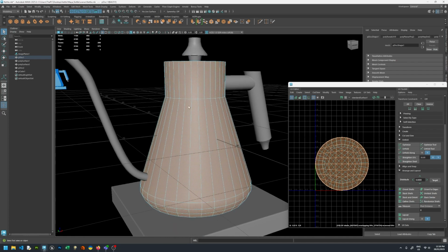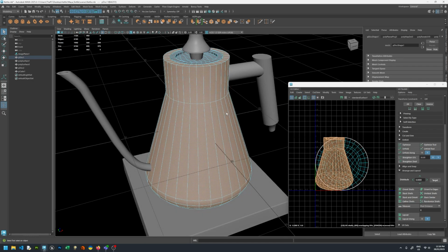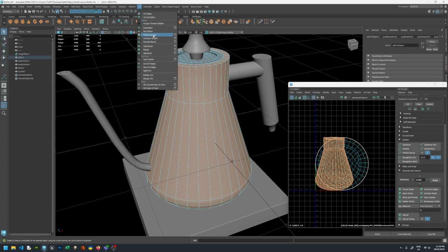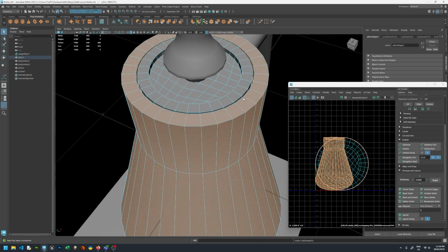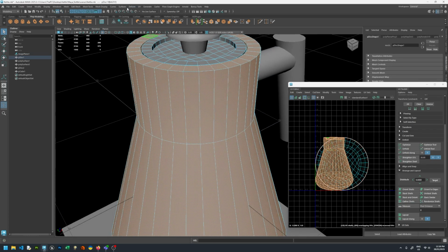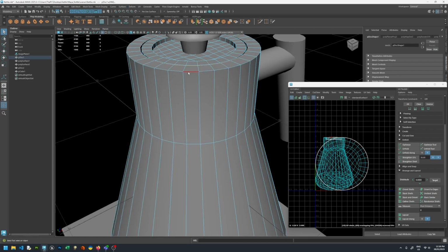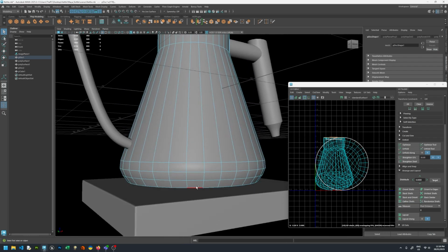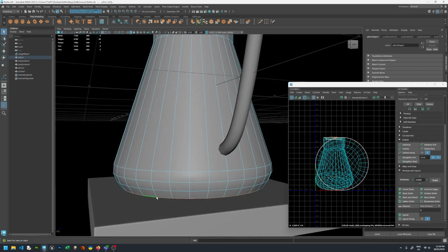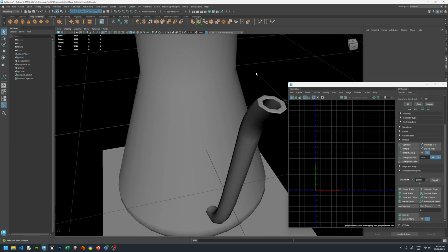Now the canister. Delete the default. Create a new camera base. And we'll use the auto seams again. Let's undo that. Auto seams seems to do everything that's attached. So we'll just cut this manually. Select all the hard edges. 2 at the top and the 1 at the bottom. Shift X to cut. And then we need 1 edge down the sides to be a seam.